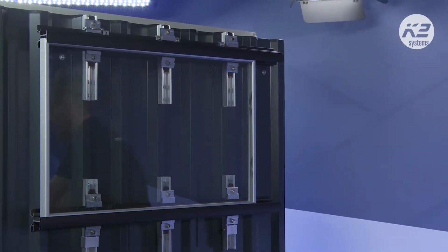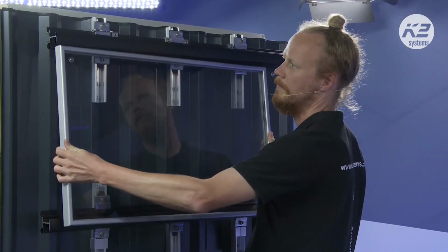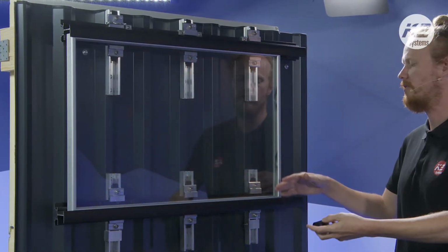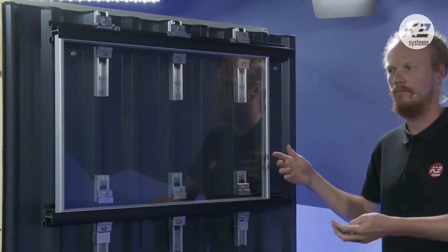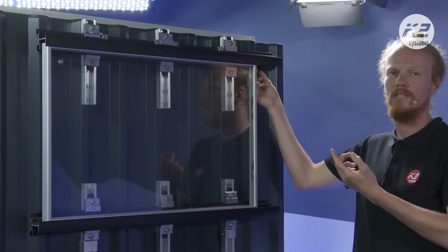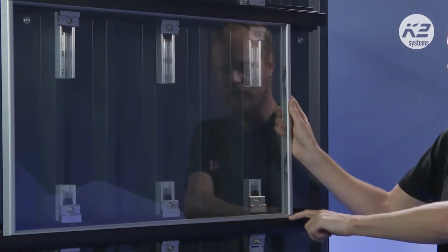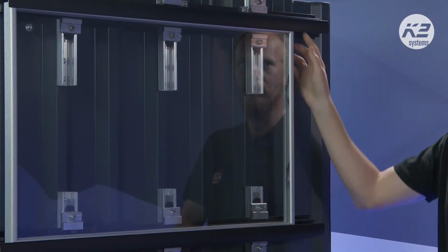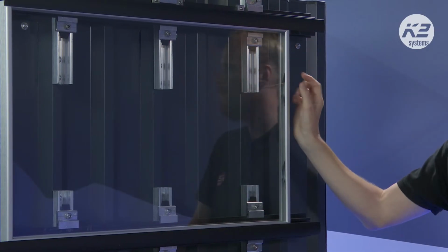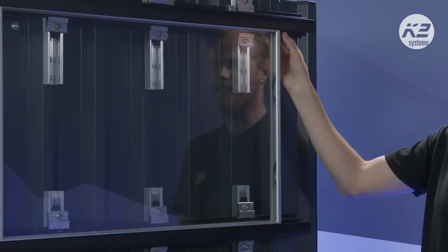So you saw this installation process, which is quite simple, sort of an up-down, right? And in some places we get questions about, well, is this going to be a secure system because someone could just come up and take it down, right? But once the stopper is in as well, it provides just enough space that at the bottom now you can see here that it's not going to come out of the bottom channel. And so once you've put this little stopper in, you're not only getting an even gap between this panel and the next panel, you're also ensuring the panels can't be taken out.